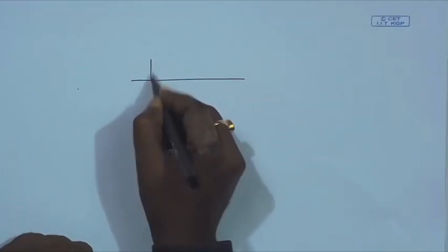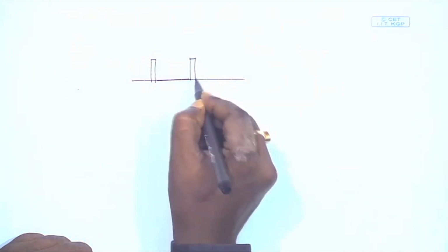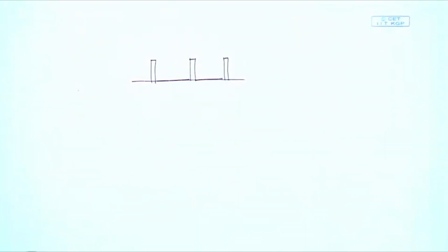So basically, in pulse modulation, instead of using a carrier like in amplitude or frequency modulation, what we are trying to do is we have a pulse train which looks like this. It might have different shapes, which is something we will explore. We have this periodic pulse train, and then we want to modulate our information on this pulse. So the pulse is almost working like a carrier.